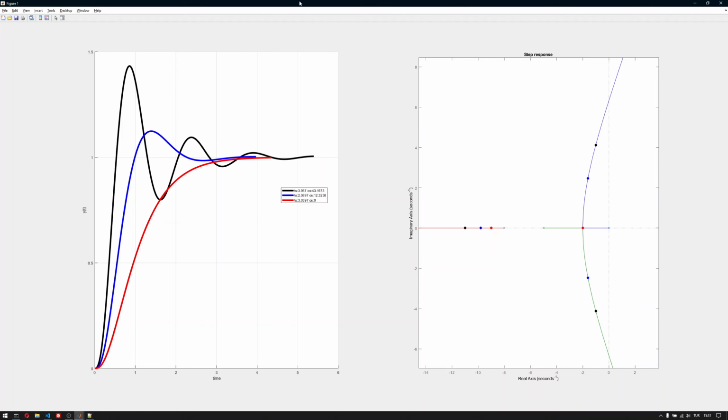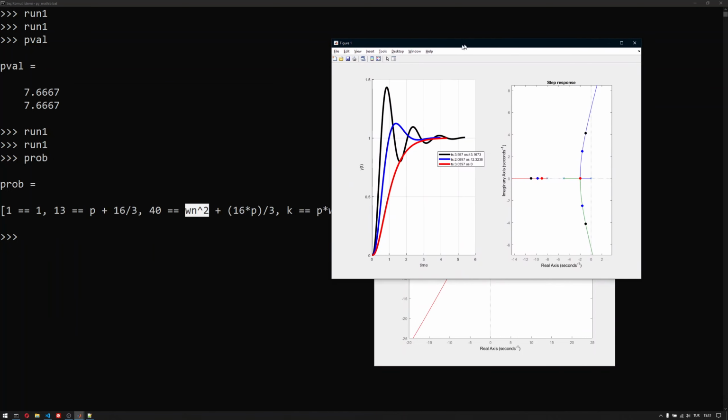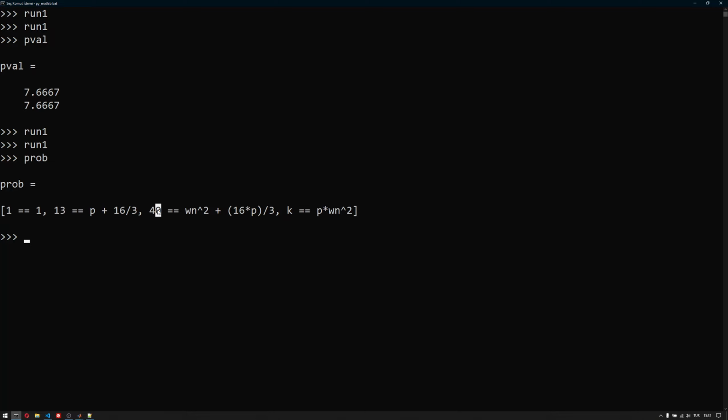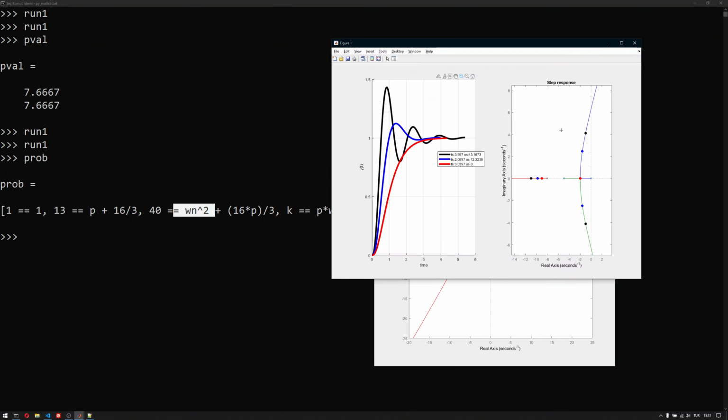But we can see that we are not able to place the poles arbitrarily because, well, we have some limitations on the coefficients. Some of them are already fixed to some values, and others might have restrictions based on the positivity of omega n. So, in short, we are limited to the root locus plot here. So if we increase the k value, we see that zeta will decrease, so overshoot will increase. If we decrease it, we will have 3 real poles maybe. That is also maybe problematic.